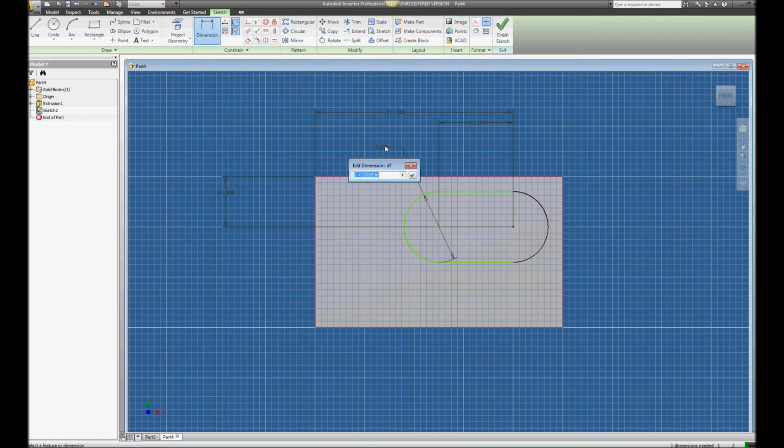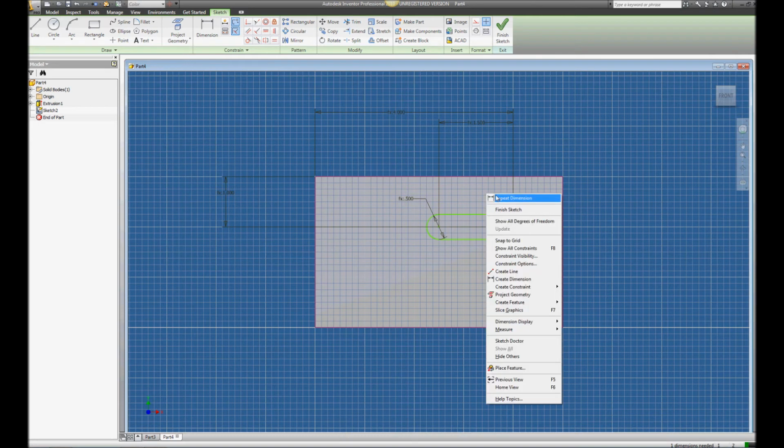Drop that in. Now, for slot diameter, it's 2 times the plate thickness. Plate thickness being D2. We're going to take our D2 and we're just going to multiply it times 2. Look at that. That looks right on. Looks perfect. Next step. We need to right click and done. It's always good to go through and check to make sure that you have functions of x. Function of x, we have all of these equations, so we did it right.